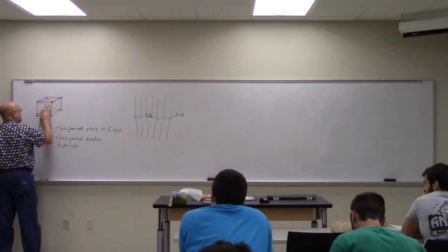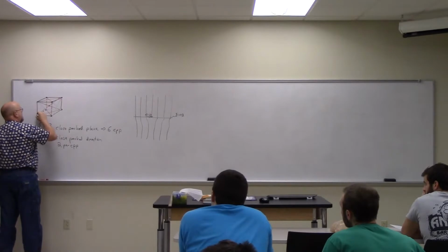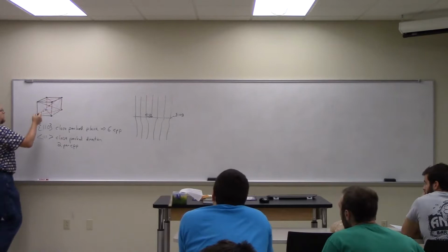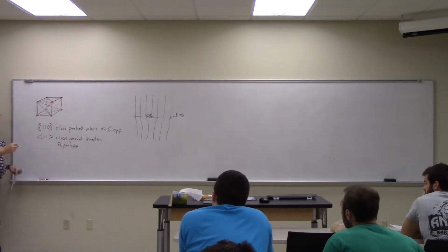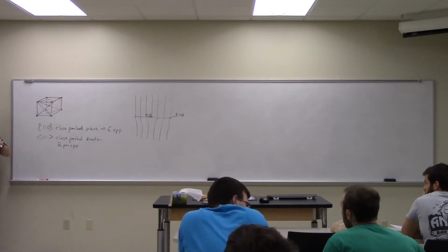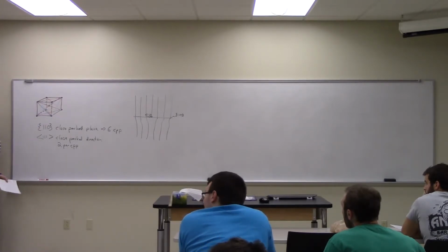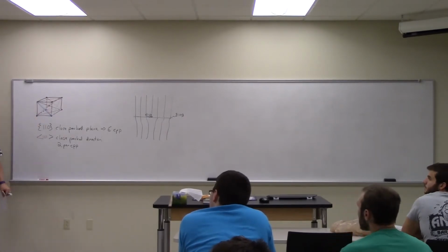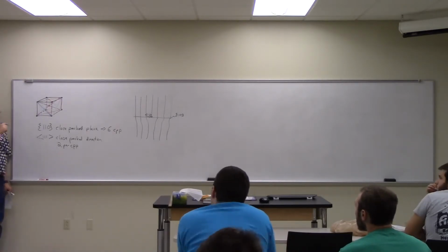Oops, didn't draw that very well. And then this one. We see those. And then similarly, there would be 2 on this face. So there are basically 2 per face, and they're redundant, the top face and the bottom face are the same. This is specific to BCC. Well, there are 6 110 planes in any cubic structure, but only in BCC are those the close packed planes.